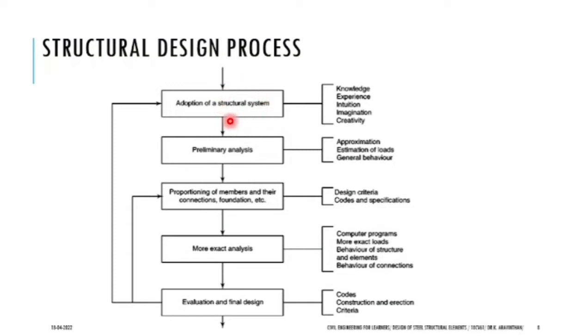For what structure you are applying this? If you are building a normal 3-story structure, load bearing is enough, and if you are going beyond that, you need shear walls. Up to ground story plus 3 floors, you can go for the column and beam type. This type of structural system is called a framed structure. These structures are built using frames. What are the frames? Beams and columns are the frames. By making a number of beams and columns, you can rise through your vertical construction.